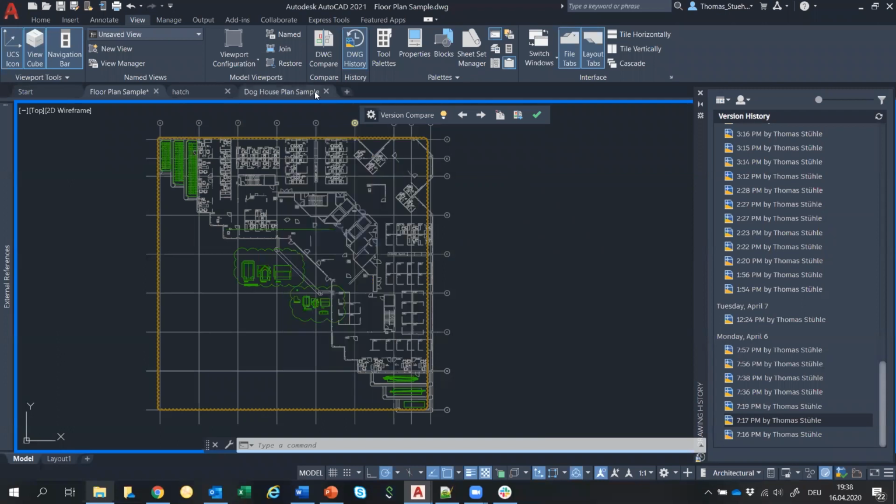What we don't have, for example, in Xref Compare, there is a button that says import objects. So if there is a component in a previous drawing that we don't have in our current drawing, you can press this functionality, select the object, and that object is directly imported in my current drawing. So you are able to get objects back that you deleted versions before.